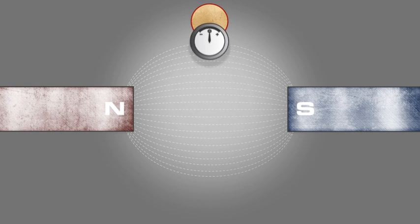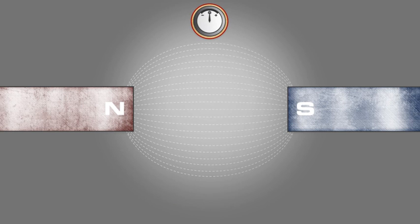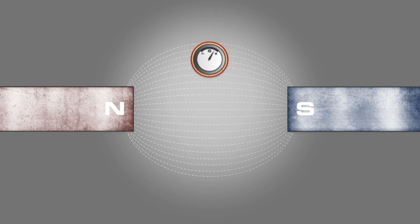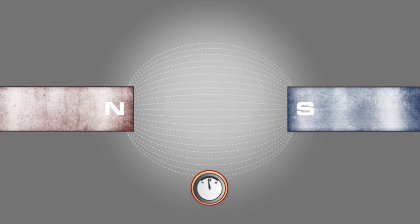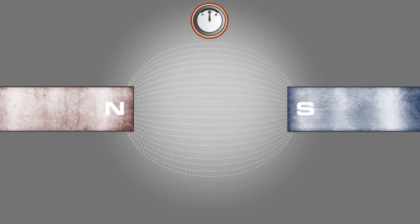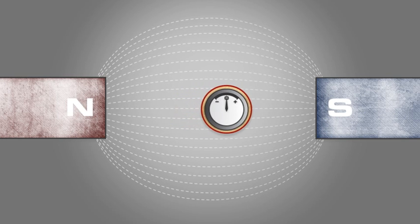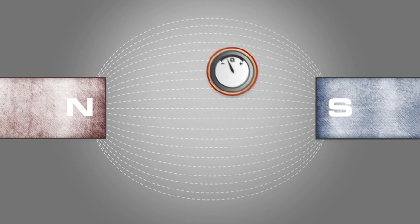By connecting a current meter to the conductor, we can measure the amount of current produced by passing the conductor through the magnetic lines of flux. As the conductor passes down through the magnetic lines of flux, it produces a current in one direction, and as it comes back up through the lines of flux, it produces current in the other direction. If the conductor is passed from left to right in the flux lines, no current is read because the conductor does not pass through the field of flux lines.